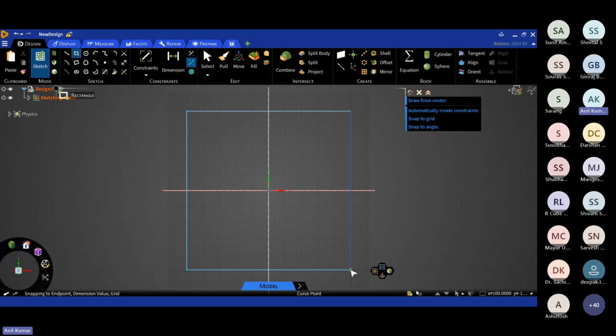Right. So for example, if we are dealing with some nonlinear materials, non-linearity we cannot consider here. Only frictional contact and sliding frictionless contact, that kind of contact nonlinearity, we can consider. But in detailed analysis, if there is a different type of mechanism with high nonlinearity, or some material nonlinearity, that we cannot consider here in static structural analysis. So the concept is that we cannot replicate Ansys Mechanical with Discovery, but the initial level of simulation we can perform in this tool.